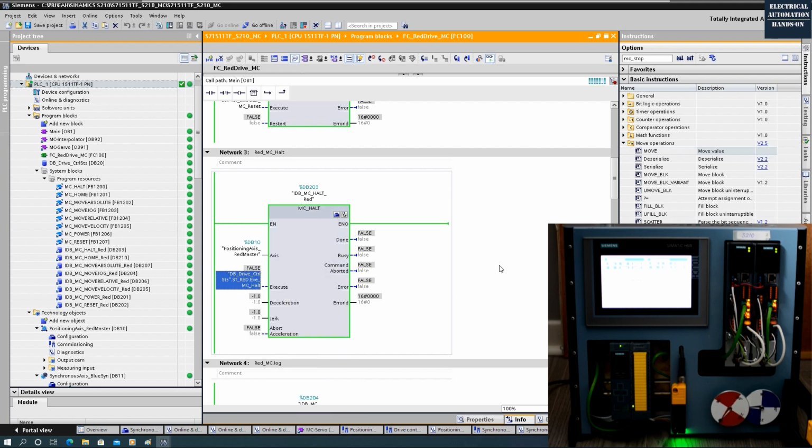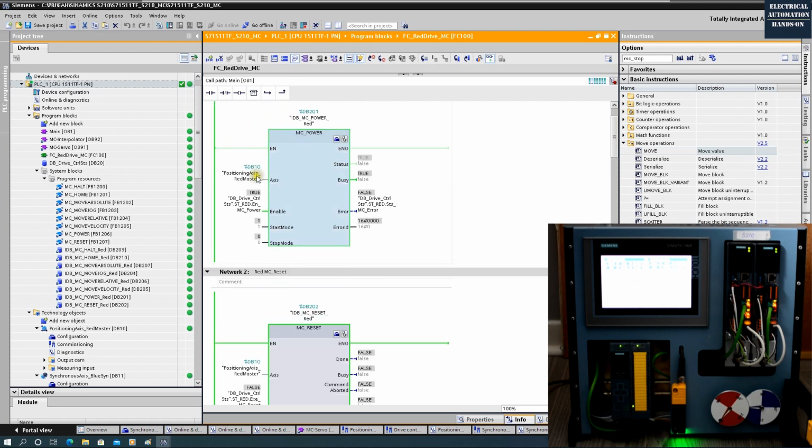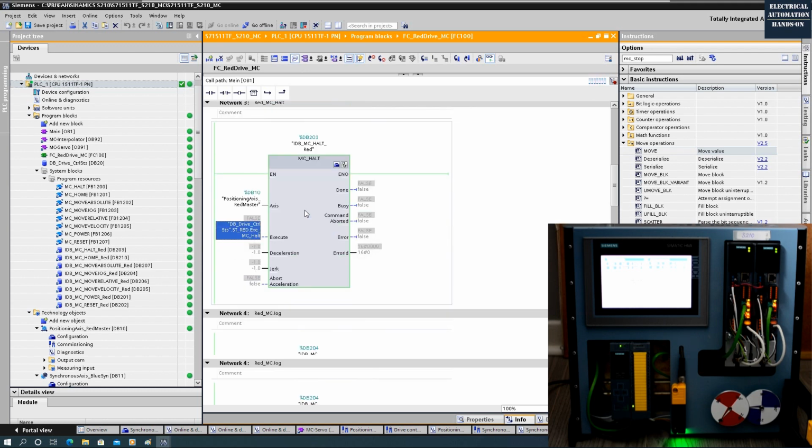This is a ramp down stop. And the deceleration, you can control this deceleration. Usually we can stop gently and slow down. If an emergency stop is needed, then you can even turn off the MC power. When this MC power turns off, it is a similar idea to the emergency stop or MC stop command to hold the drive. Okay, so we can do a quick try.